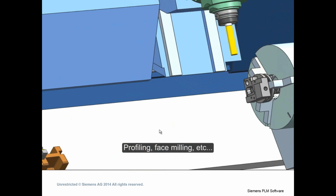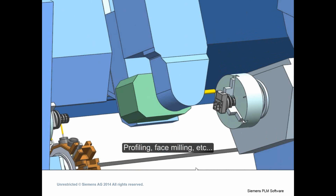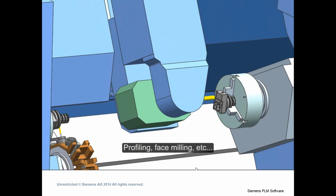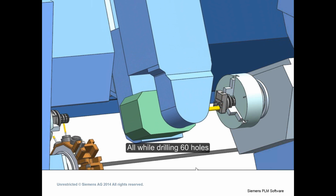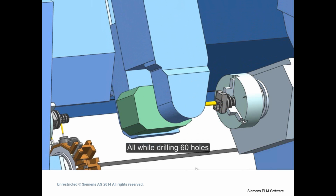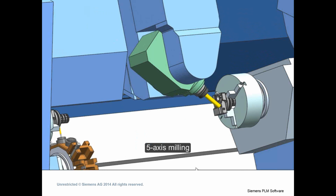Here again we can see the toolpath verification, some chamfer milling operations going on. Now we'll finish the face milling on our part, moving on to do some 5-axis machining inside of the small cavity on the top of our part, all while still drilling our 60 holes.